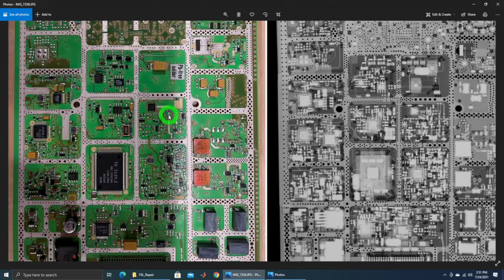So the signal coming over here is coupled into multiple places, and some of it right over here is coupled back through here into this, and then this eventually finds its way over here. Here's a reference over here that also finds its way to here. This is most likely a synthesizer chip then and works with this phase frequency detector closing the loop of the PLL. So this is where I would probably pay attention to. Any of these components in the chain can totally mess up, of course, the synthesizer. And there's a whole bunch of other filtering over here, some lower frequency filtering. These are inductors, of course.